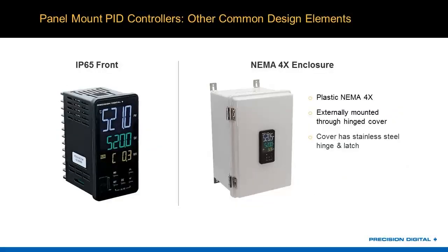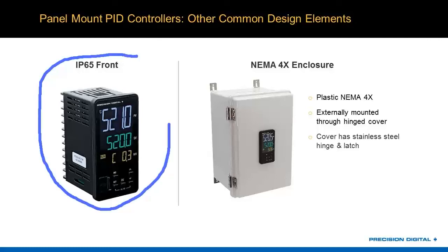Other common design elements you're going to run into in PID controllers, they are often IP65 fronts. That is compared to NEMA 4X. Somewhat equivalent. It's proof against water ingress up to certain pressures and volumes. It's dust tight. But because PID controllers are very much universal in the way they look, the bezels tend to be designed a certain way, and so they tend to be IP65 versus NEMA 4X.